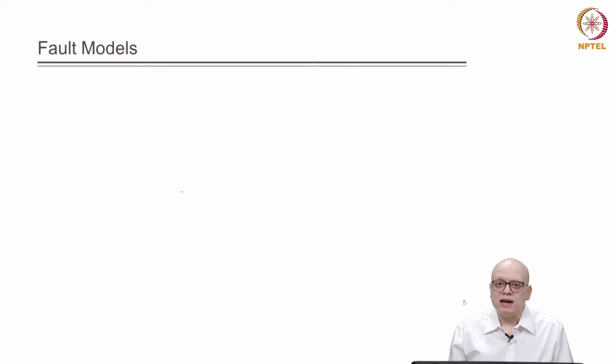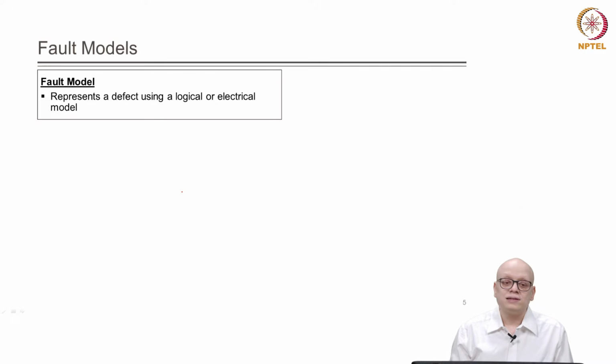Now, the manufacturing test is done with the help of fault models, right. So, we design test methods or extract test patterns by assuming a fault model for our circuit. Now, what are these fault models? Fault models represent a defect using a logical or electrical model, right.